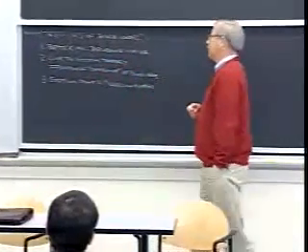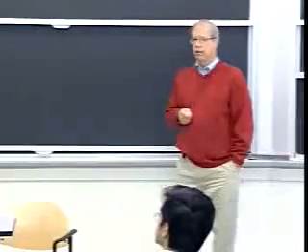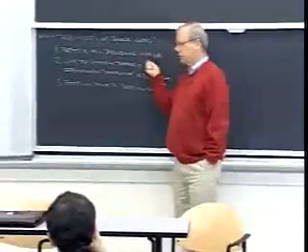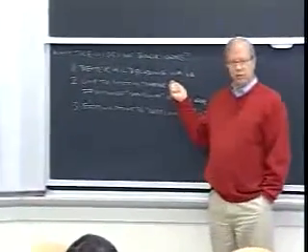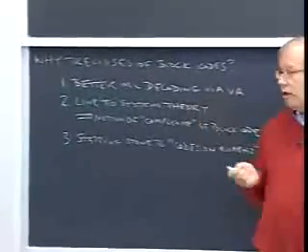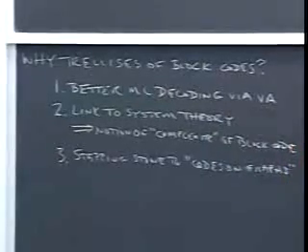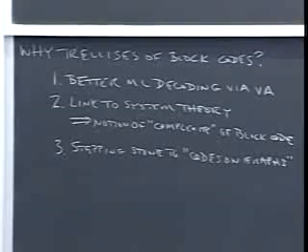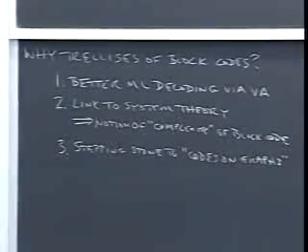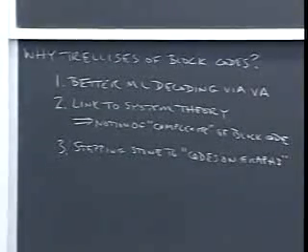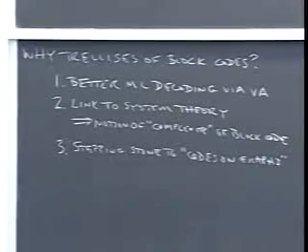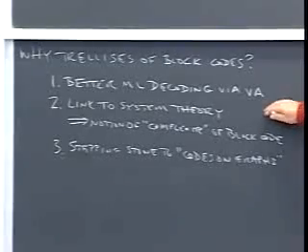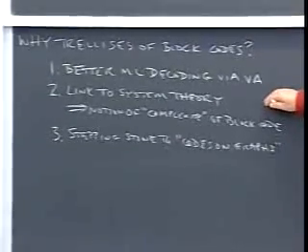All right. So the reason we look for trellises of block codes is, first of all, it's better than exhaustive maximum likelihood decoding. It is a maximum likelihood decoding algorithm, since we're going to find that we can construct a trellis for any linear block code, which at worst is never going to be more complicated than just enumerating all the code words and doing exhaustive maximum likelihood decoding.